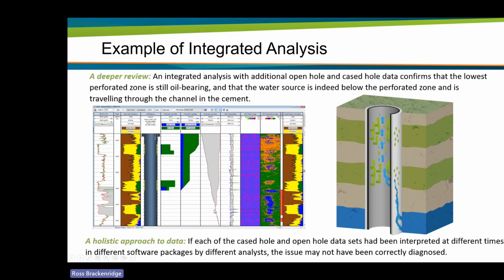The temperature between shut-in and flowing, this spread here, also indicates that there's likely to be something flowing behind the casing. Casing's in good condition, so we don't have any leaks to worry about. But look at the cement. The cement has what looks like a channel coming from that bottom perforation deeper into the well. If we look at our pulse neutron data, we see that actually this zone looks still oil bearing. This bottom zone looks water swept.